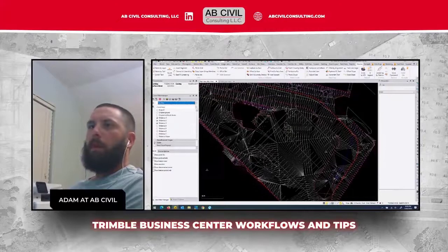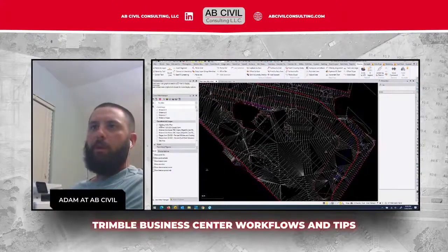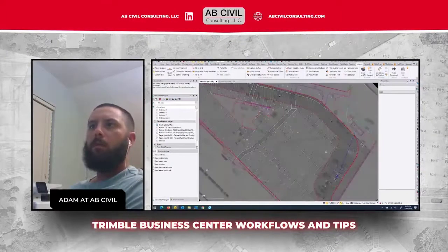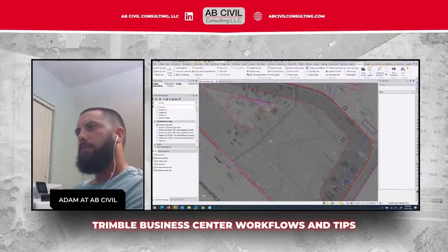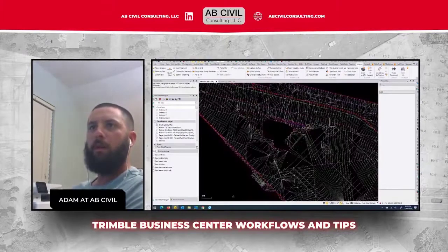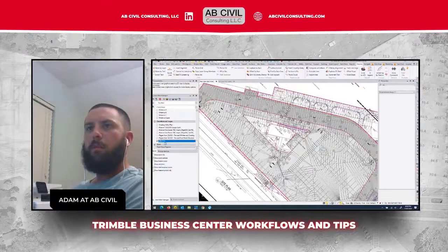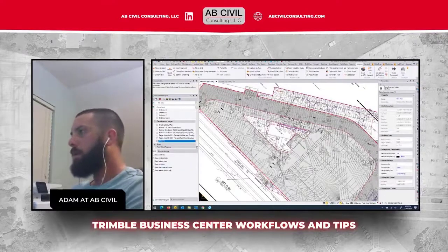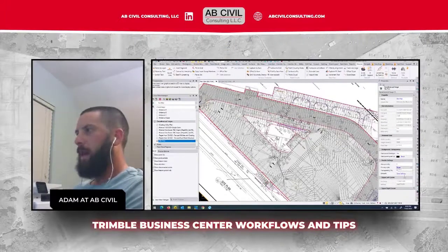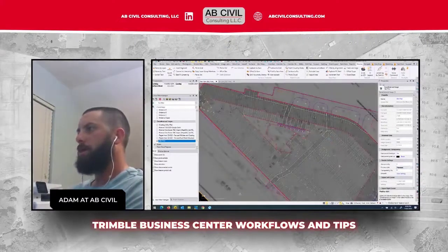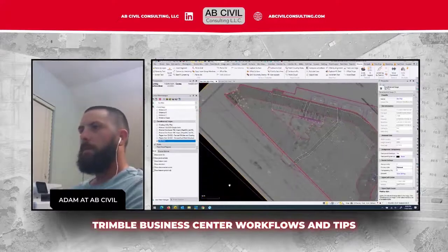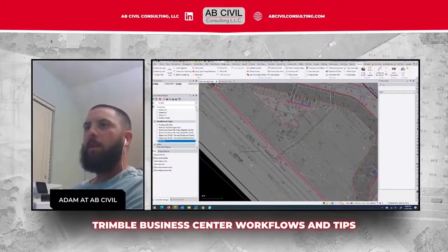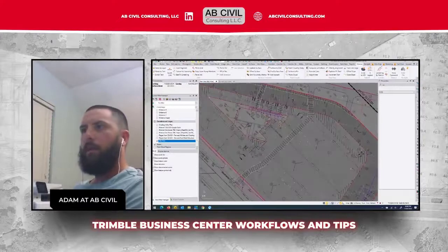Now, I've got my PDFs geo-referenced in here, which every model I build is based off of. Grading, utility plan, it doesn't really matter what you choose. I'll probably choose the site plan. So right click on site plan and properties. I have none on display style. Normally I have it dimmed, but there might have been a reason why I switched it. So I'm going to put it back to dimmed. Now this is in plan view, of course, and I want to see this on my surface.